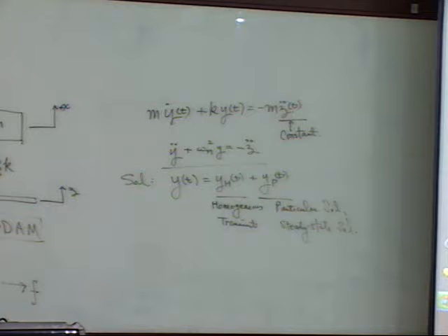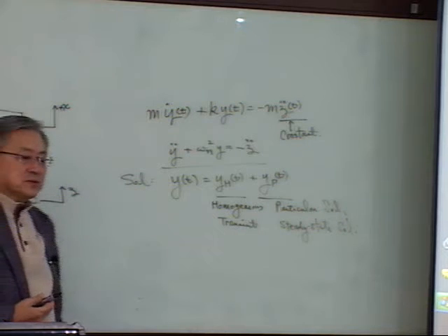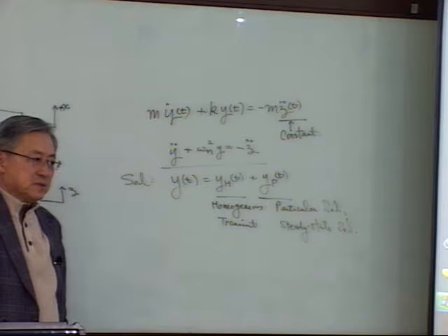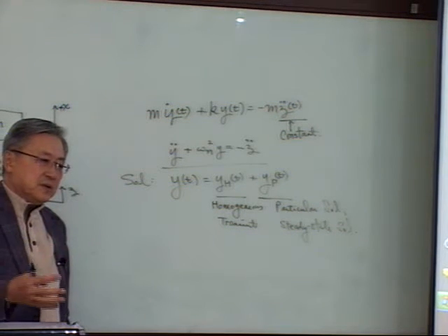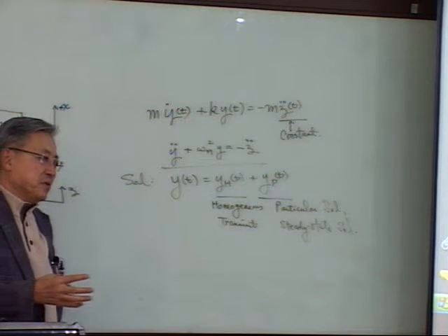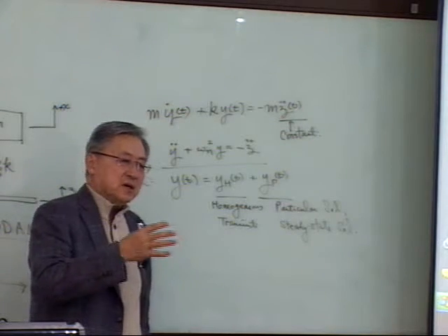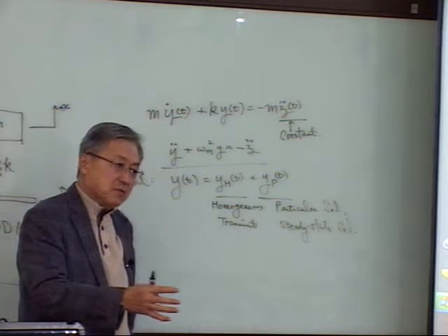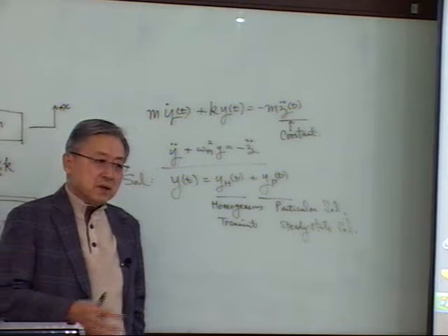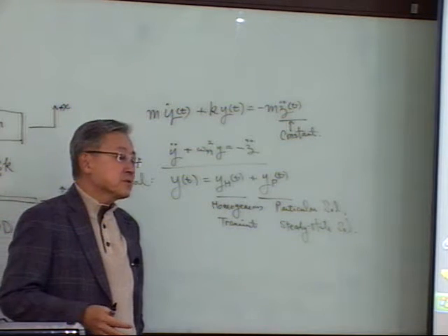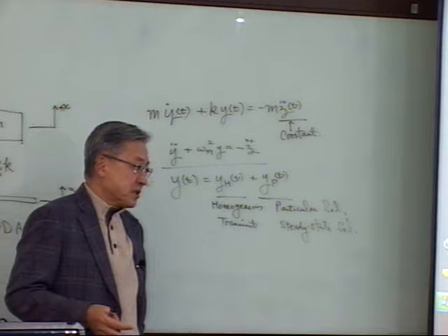And a homogeneous solution is like this for the startup solutions. Or you can call it the free vibration solutions. Startup. When you start the machinery or you start the ship, then the shaft starts to roll. Okay, the shaft starts to roll from 0 to a certain RPM. RPM is revolutions per minute. You can convert it into hertz. Cycles per second, okay?